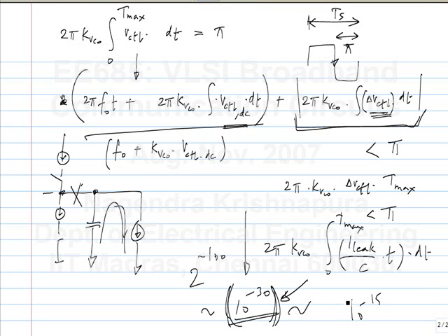Okay. All I'm saying is if you design it for a long enough string of consecutive identical digits, the bit error rate because of this will be so small that you would not be worried about this. Okay. So yeah, that's what it does. Eventually, I mean, you can evaluate the bit errors based on how far it drifts and how it corrects back. Okay.